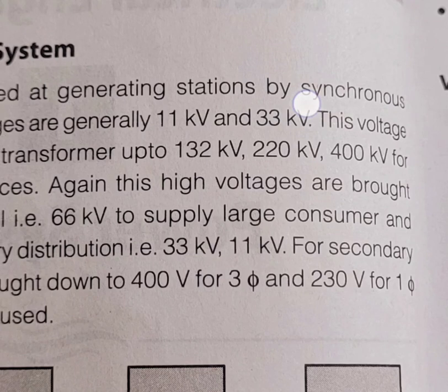Okay, understood? One question should be in mind: why are we not converting our whole system to a 60 hertz system? Because our old systems are from when we were a colony of the British, so they gave us 50 hertz, and after that we kept going that way. If we change now to 60 hertz, there will be a huge economic imbalance. We have to change everything, and every system's insulation and everything. That's the problem. That's why we opted for 50 hertz.